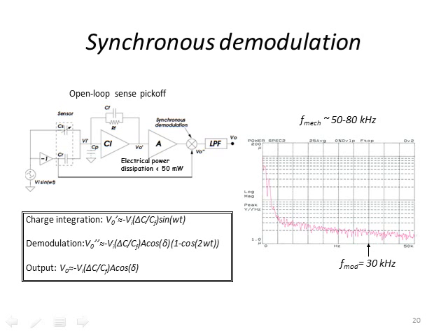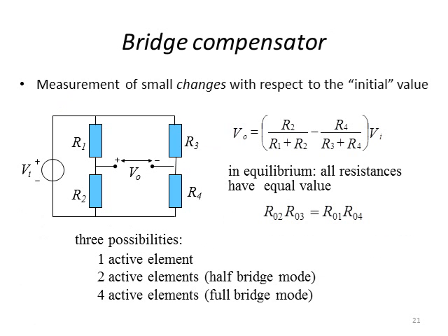And then we have this synchronous demodulation where we modulate on the lower left. You'll see the input. And then we also multiply a -1 to our reference. So then we want to subtract any noise. And then we take this into the integrating amplifier. You see our RC pair, and then we amplify it. And then at the end, we remove this modulation component by doing synchronous demodulation and then a low-pass filter on the output to remove noise on the output.